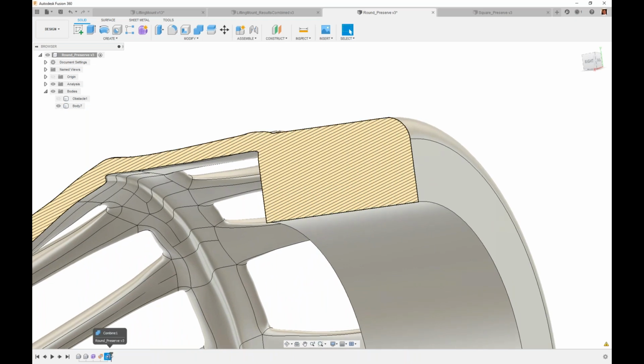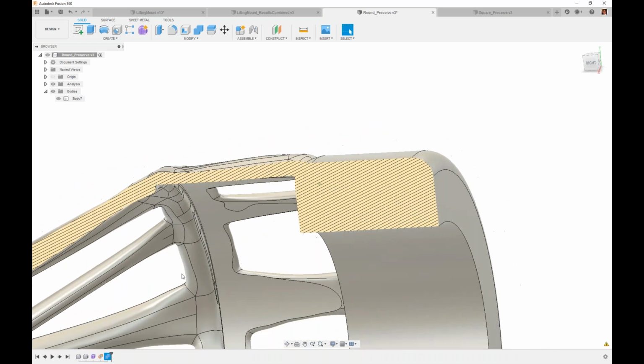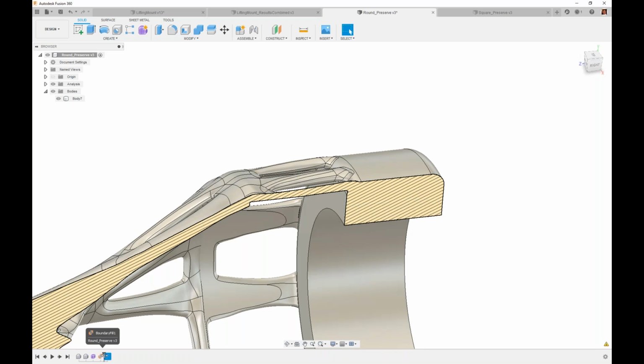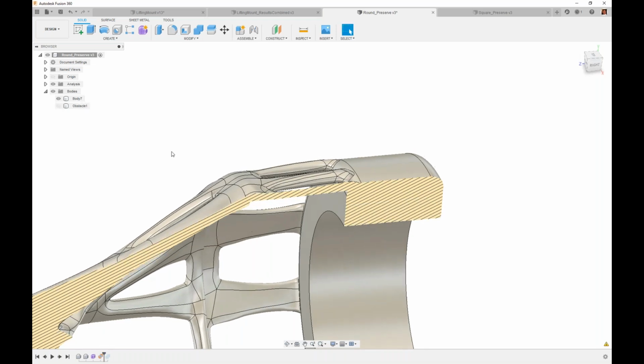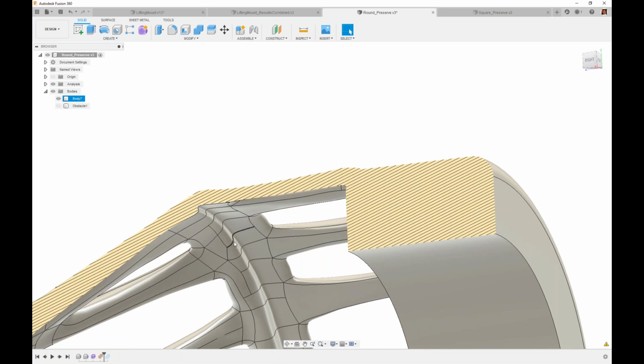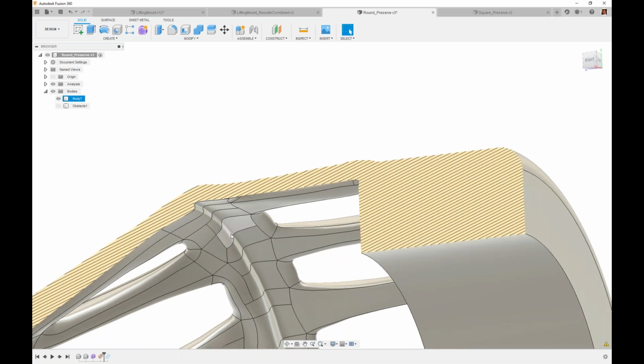If you look at it between that and that, we get this sharp edge because of that subtraction. So in many cases, if I can, I'll oversize that obstacle region so that in my final outcome I don't need this last step, and I'll have a cleaner T-spline for modifications, and one that should easily clear the actual obstacle.